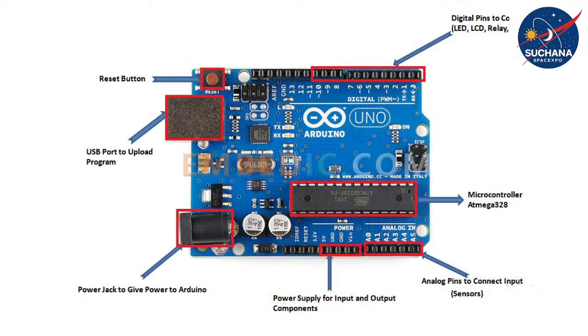So later, when you give it an external power supply, the LED still blinks programmatically at whatever time interval you specified in the program. Because the program is in the microcontroller, it is stored in the non-volatile memory. You power up the Arduino module with a battery, it gets power supply, and then the program gets executed. That's how the LED blinks at the same time interval that you provided in the program.